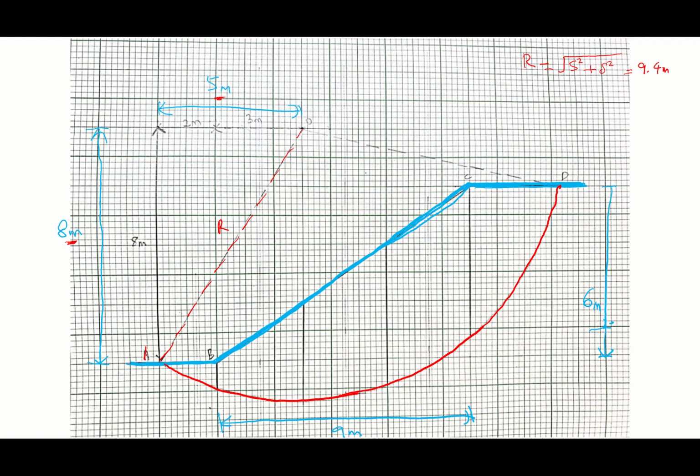So we have from line A to line B here. And then next is to plot the information given onto the graph paper. Okay, meaning that you are plotting the semicircle, but using R equal to 9.4 meter on the origin point. Okay, this is your origin point 0, 0. Draw the circle that connects point A to point B. And then make a dotted line connected from point A to O and from O to B.